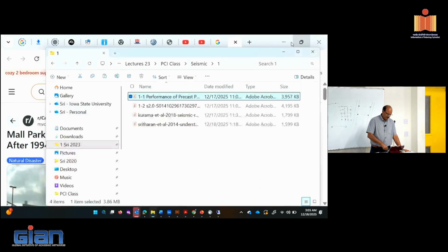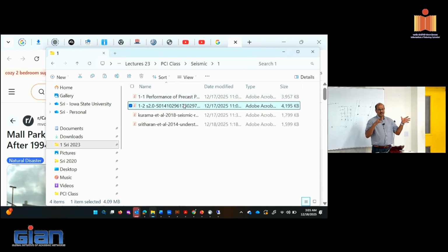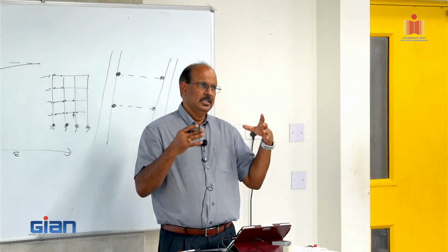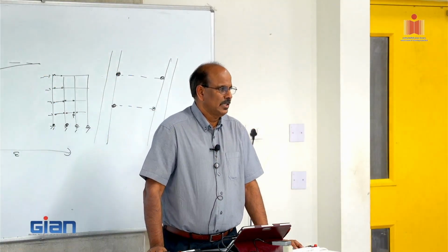The Japanese earthquake, the Kobe earthquake, brought damage to the system, but it didn't bring structures down. Japanese tend to do two things differently. One is, we all use capacity design. I don't know if Professor Amalan talked about allowing structures to basically go through inelastic motions, right? So inelastic deformation, so that structure can be designed more cost effectively.